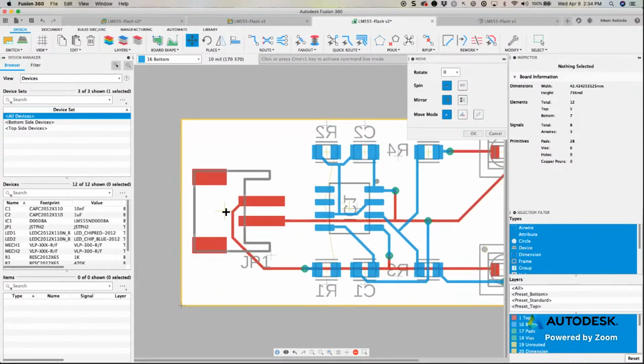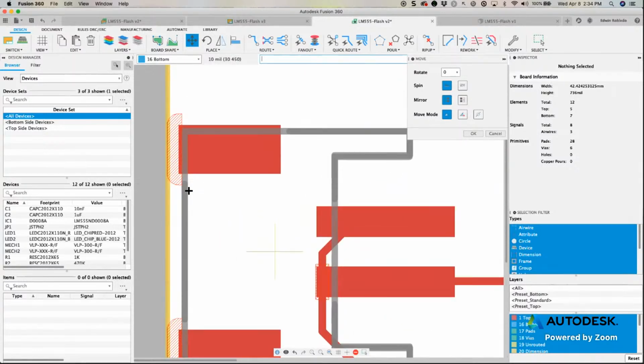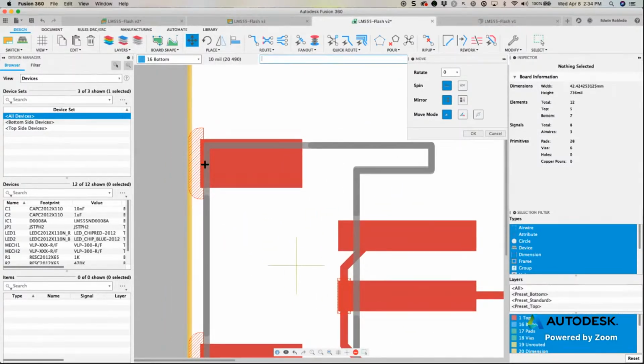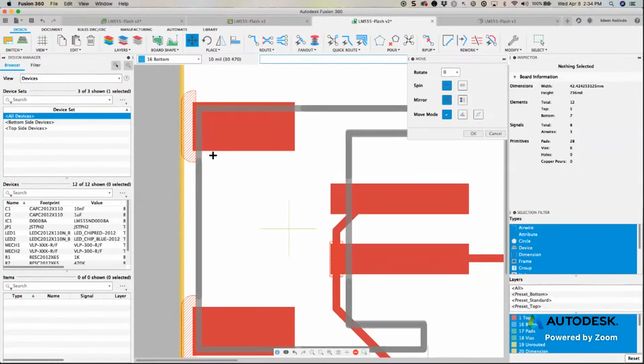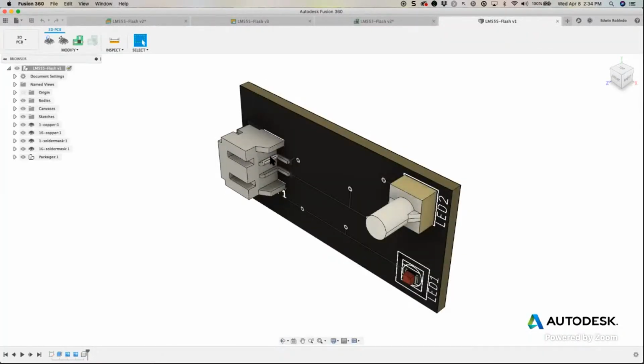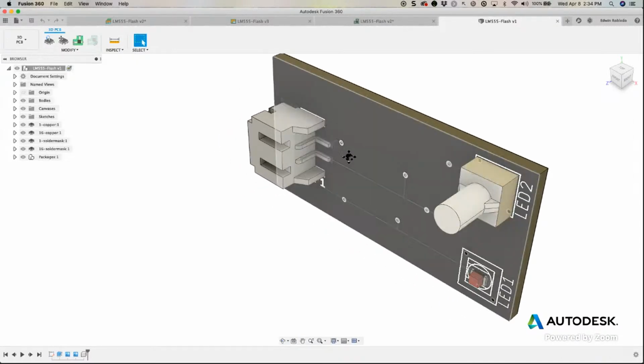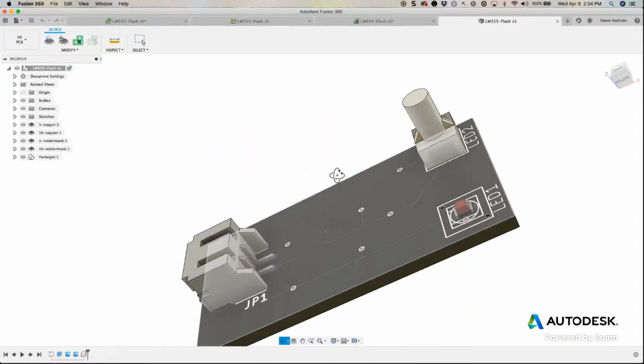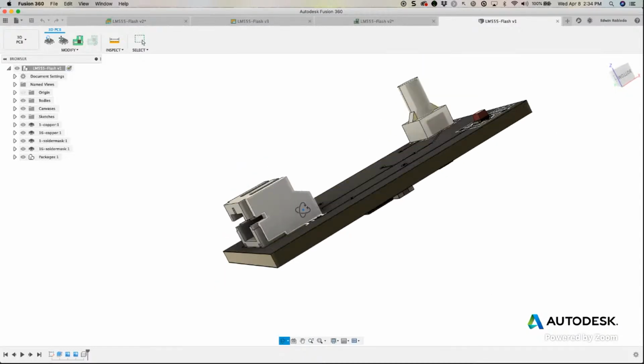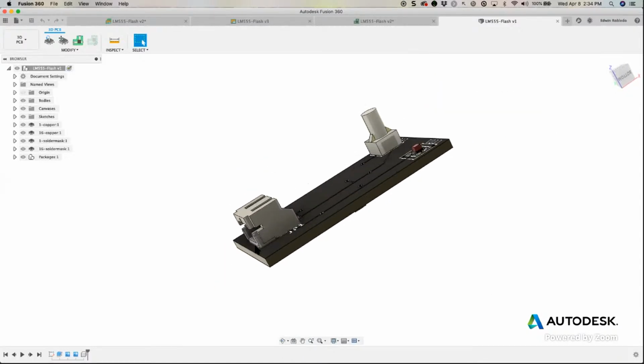I'm just going to go ahead and move this connector. And as you can see, we get the violation because I am actually below the 30 mils. Now, there'll be instances like this plug where I would most probably take it to the edge because it's a side plug. So I may actually violate it anyway because I want that to be sitting on the edge of the board, as you can see here.